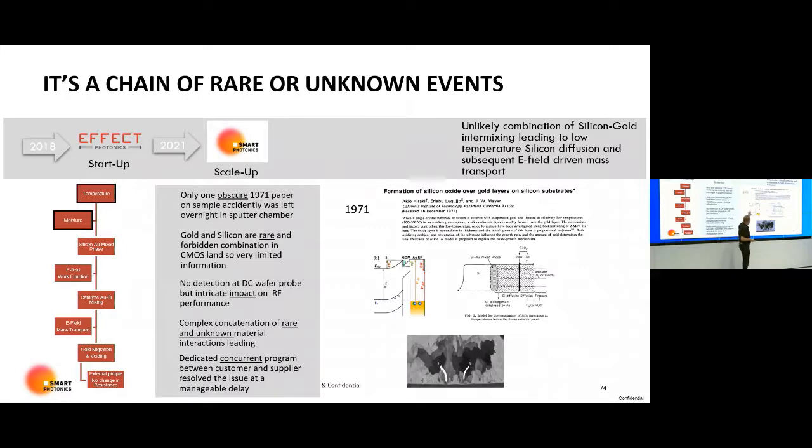That tilts the work functions and catalyzes this gold-silicon intermixing. The silicon is actually dissolved, so we get a liquid of gold and silicon at 85 degrees. Then the electric field from the electrodes pulls the gold along the field lines towards the side electrodes of the coplanar waveguide.